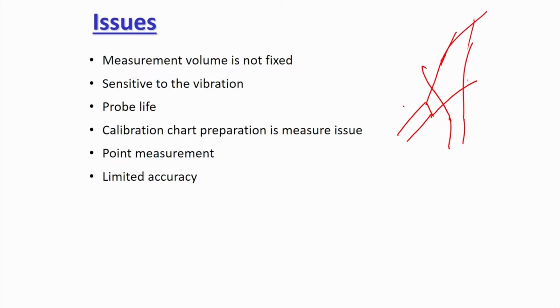If I fix my measurement volume, say this, though it is very small, what will happen? If a bubble is there in such a way that one bubble is occupying the whole measurement volume, I can detect it, okay, this is a bubble, and that formula can be used with the pure gas and pure liquid calibration.